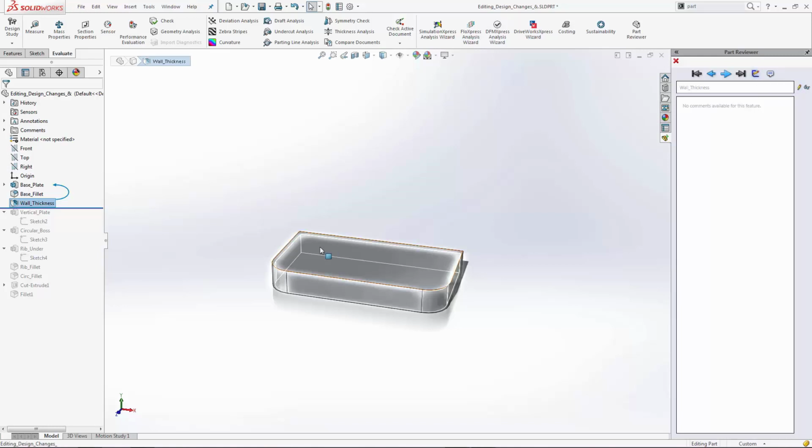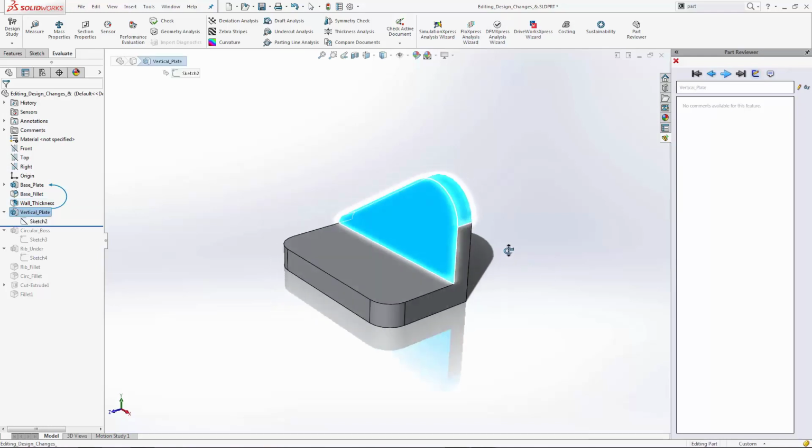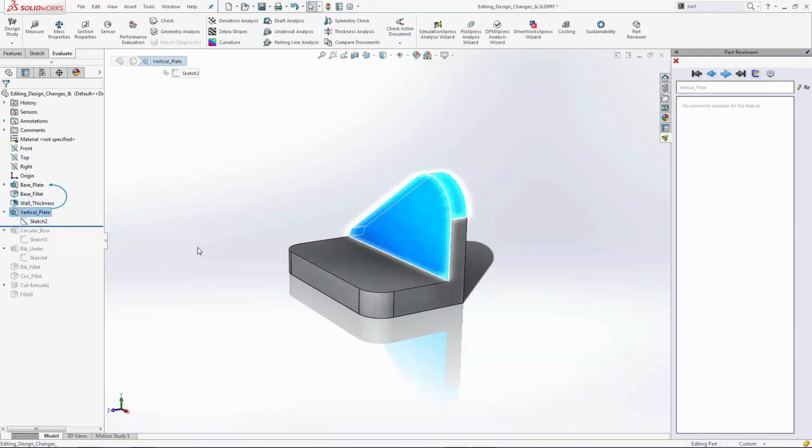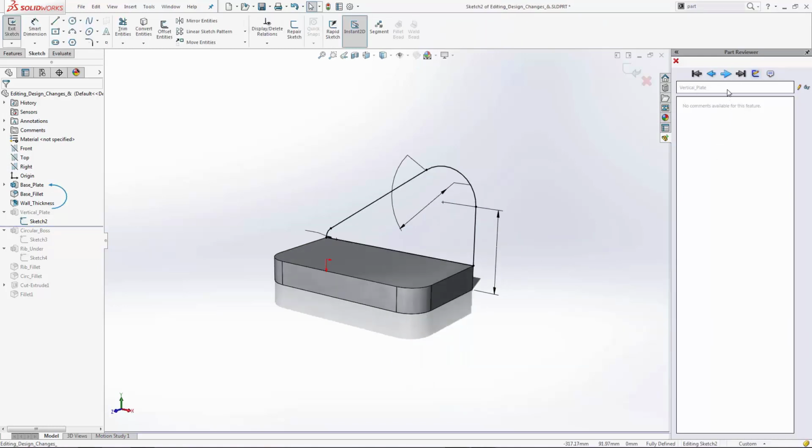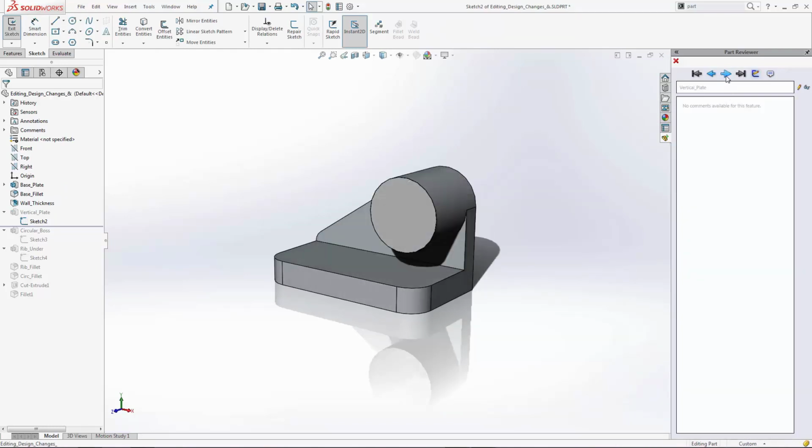We also have the ability to turn on and off the sketch details. So by toggling that on, when I go into a part that has got a sketch underlying it, you can see that the sketch is absorbed by the feature. So if I click Next, we'll be able to see that. I'll continue to work my way through this part.